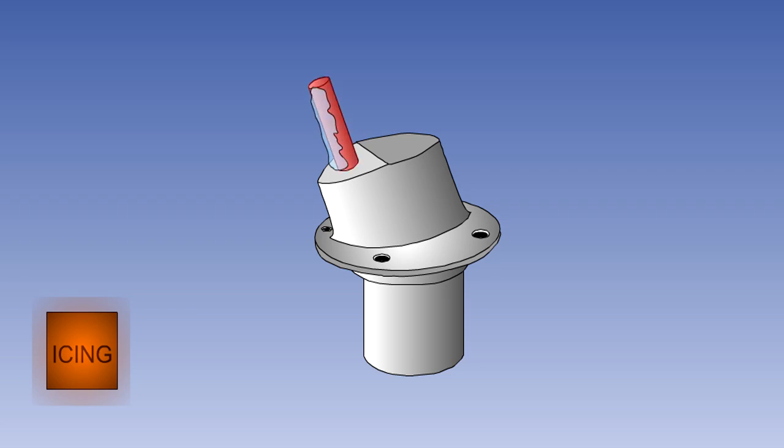When the ice warning is given, a built-in heater element heats the probe, which melts the accumulated ice, allowing the vibrating frequency to return to normal and the warning to stop. After 6 seconds, the heater switches off and the icing cycle recommences. The frequency of the cycle may be measured to give an indication of the ice accretion rate.